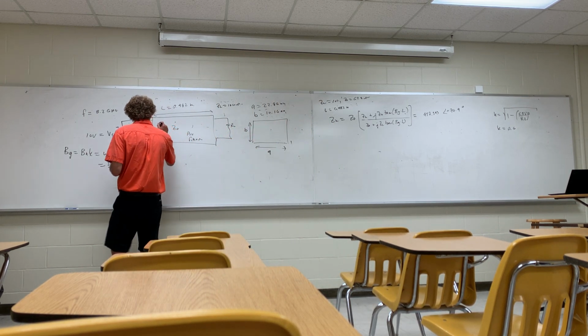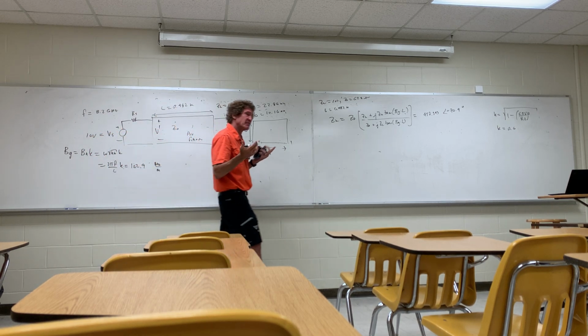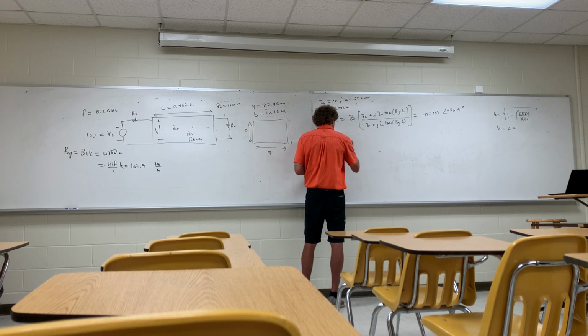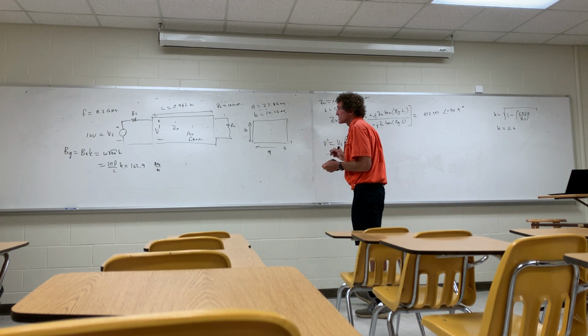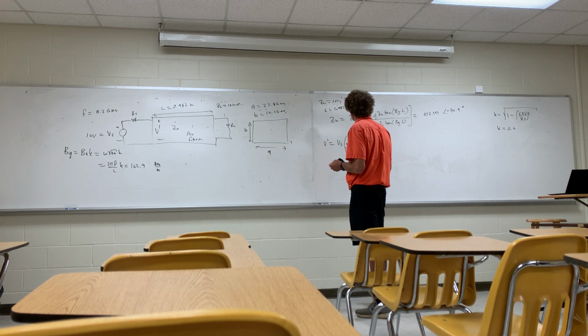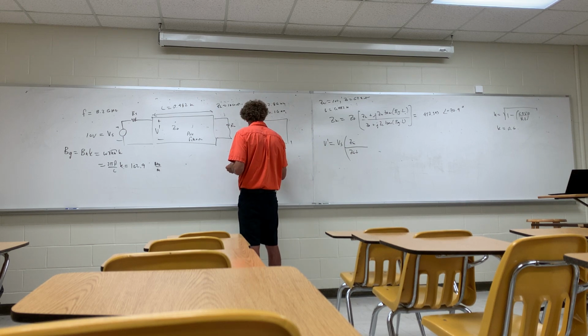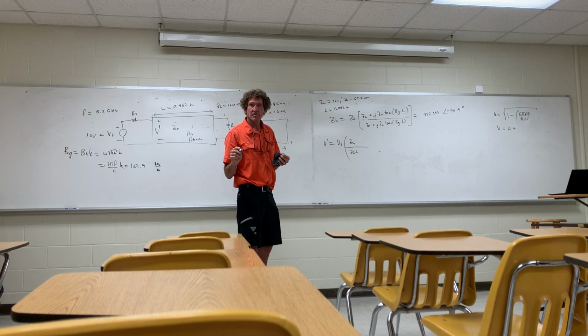inside here, we gotta get what I call either V prime, or you gotta indicate Vn, something like that. And V prime here is just gonna be Vs times Zn over Zn plus, in this case, Rs, and Rs was unstated. What was Rs for the problem? Well, I didn't write it down. So 100, 200? Rs is 200. The 200 guys? All right, 200.